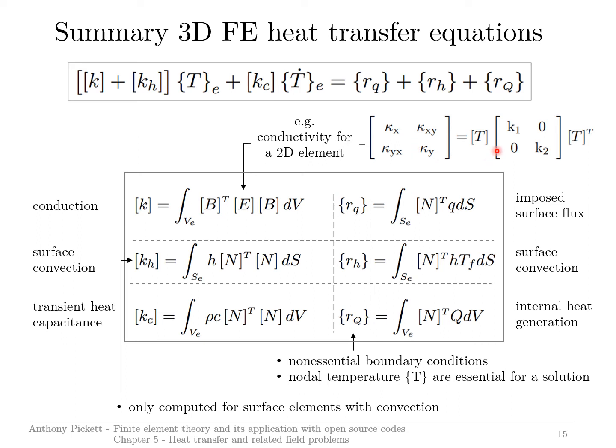If, for example, these properties varied with temperature, then it would become a nonlinear problem, and you would have to use a nonlinear implicit method like Newton-Raphson. If the boundary conditions changed with temperature, it would also be nonlinear. You could also imagine cases where you're doing a coupled heat and mechanical analysis, and if the mechanical properties are temperature dependent, that would also be a nonlinear problem.